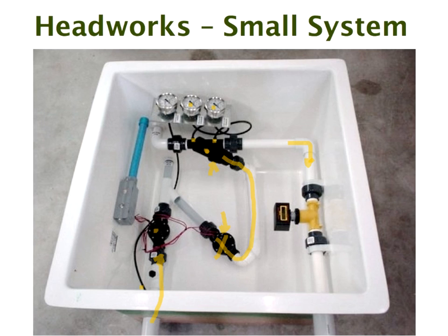What you can do with a manual valve, though, is open it a crack so that it flushes continuously. It doesn't need to be flushing at high velocity, but just flushes continuously so that the material that's deposited on the screen or on the disk gets flushed away continuously. That's quite frequently done with a manual valve there. Look, it saves a lot of money. I'm not going to argue against it. If it was my own home, I think I'd go for a solenoid valve. But, you know, one can't argue. There are so many systems out there with cracked open manual valves. I can't for one moment say that they don't work.